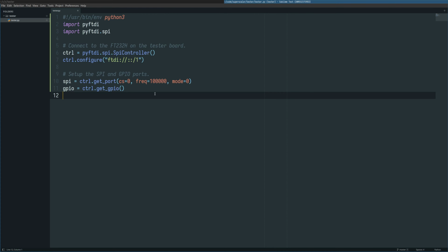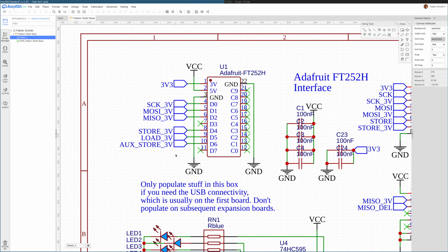And next up, we have to tell the GPIOs whether they're inputs or outputs. By calling this set direction function, we tell the library to change the direction of the upper 4 bits of the GPIO, so that's pins 4, 5, 6, and 7, and turn these into outputs. If we go back to our schematic, this hex F0 corresponds to all the upper 4 bits here, the ones we've used as GPIOs, to be enabled as GPIOs and to be outputs so we can drive a value.